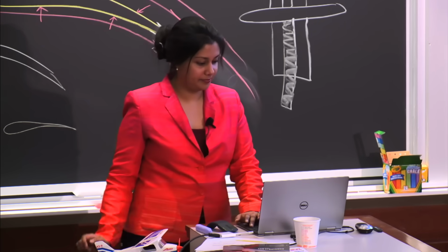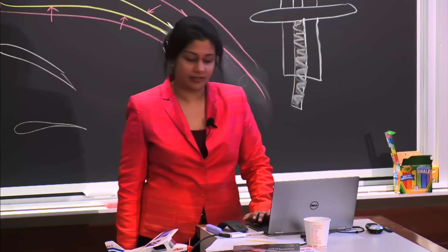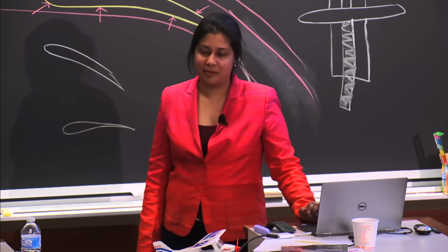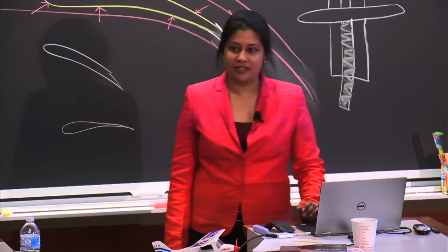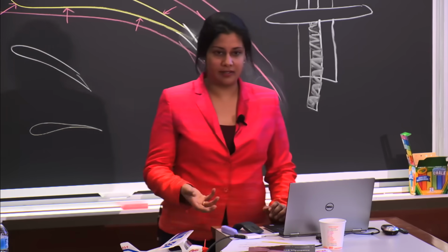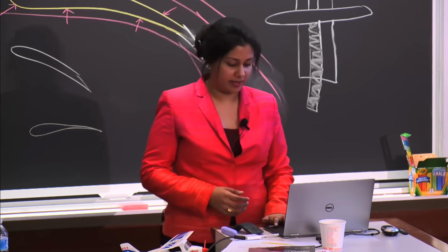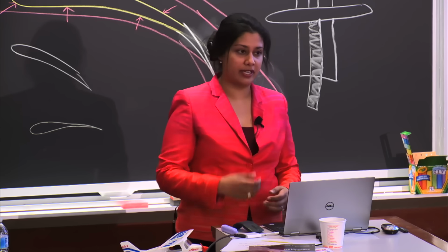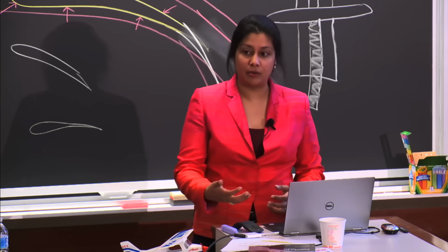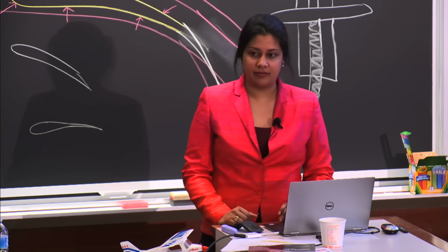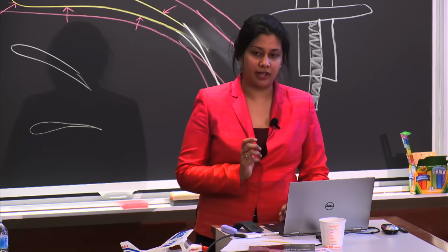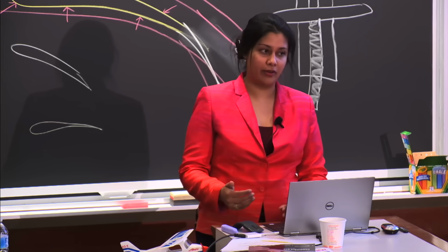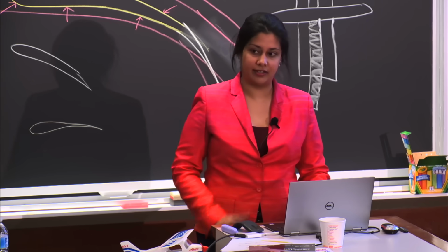Thanks. I have a simple question for you, maybe. Just to help me remember, why is it called P factor? What's the P for? Power or propeller? The P is referring to the propeller, right propeller more than the left. It also usually happens when you're at a higher power. Some flight instructors like you to think about when you have higher power in the airplane, you'll need to put on more right rudder to counteract that left turning tendency.